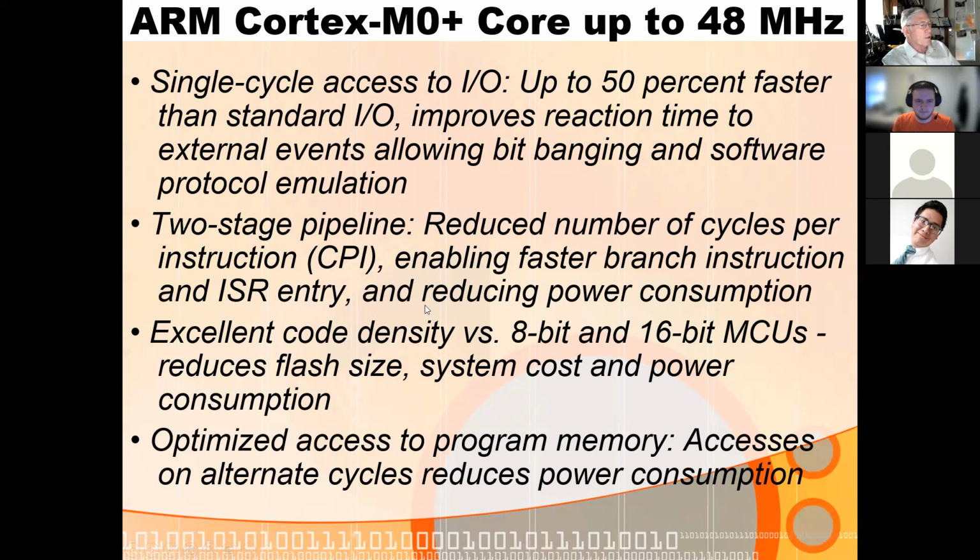With the Thumb 2 instruction set, almost all instructions are 16-bit instructions. There are a few 32-bit instructions; 6 of the 56 are 32 bits. The rest are 16 bits. So this is nice because it means your code is a little more dense.